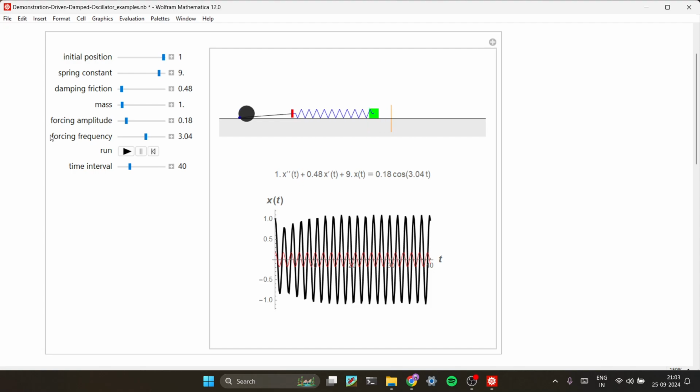And what is the applied frequency? The applied frequency is here close to 3, right? So here you can see due to this equality, there is an increase in the oscillation amplitude, right? So this is not exactly the state of resonance, but the system is near resonance. Because if I put 3 here, the system will stop here because it will encounter an infinite, a large divergence in this amplitude or the position.